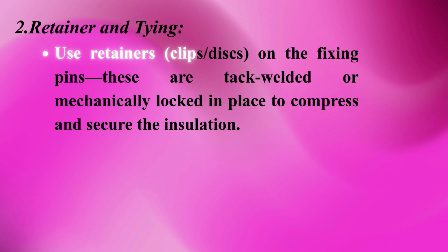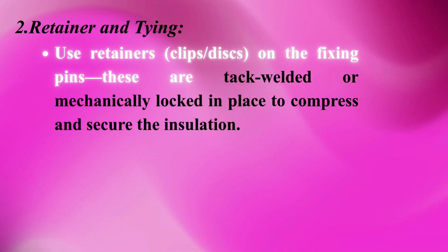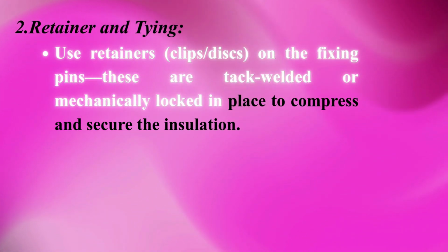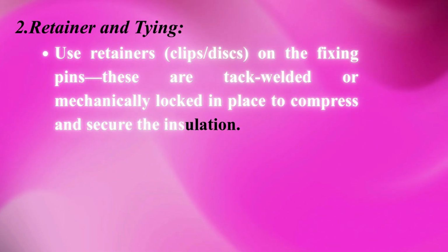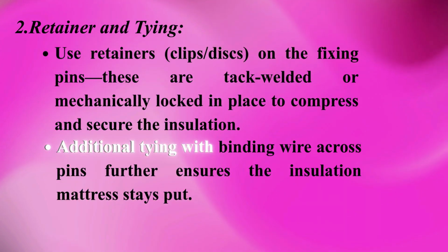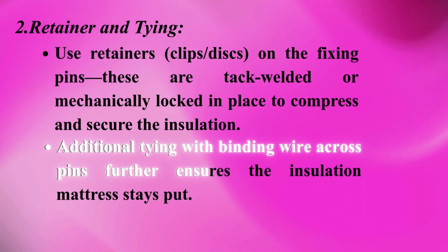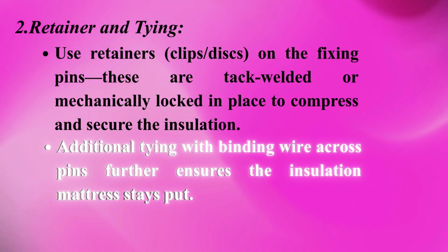2. Retainer and tying. Use retainers, clips, discs, on the fixing pins. These are tack welded or mechanically locked in place to compress and secure the insulation. Additional tying with binding wire across pins further ensures the insulation mattress stays put.